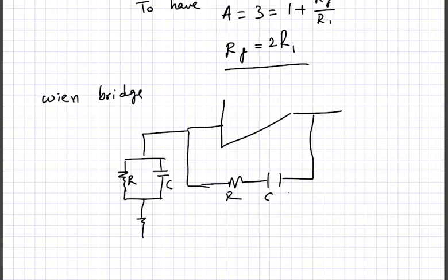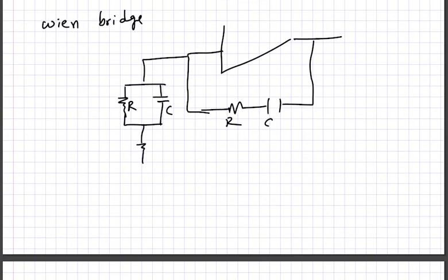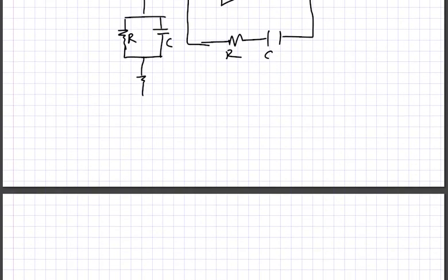Okay, bottom part. The oscillator is called Wien bridge oscillator because the resistors R1, RF, series RC, parallel RC, all of these together form what is known as the arms of a Wien bridge. Under stable oscillating condition, the bridge is balanced.